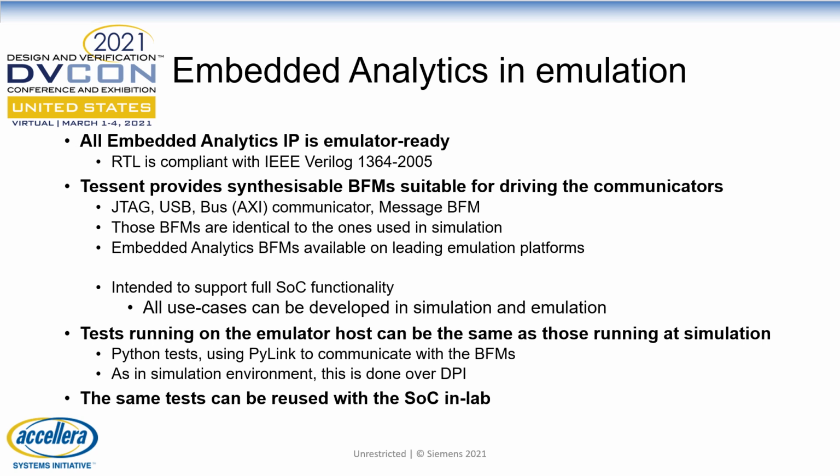Tests being developed for running on an emulator host can be the same as those developed for running in simulation and vice versa. We write many of our tests in Python using our PyLink software environment to communicate with the BFMs, and similar to how it's done in the simulation environment, the communication between the test and the emulator is done over a DPI connection. It is interesting and important to note also that the same tests can be reused with the SoC in lab and in life, so your investment in writing the test is maintained across multiple environments and use cases.